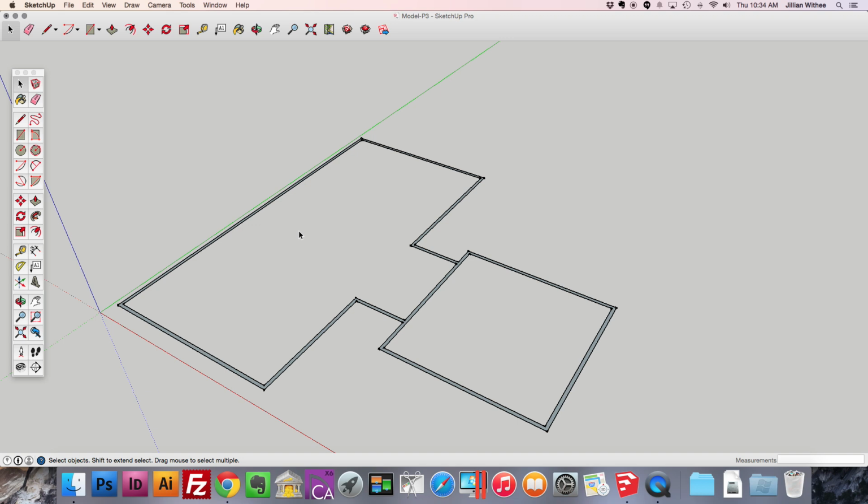Today we're going to continue learning how to draw a two-dimensional floor plan in SketchUp. I have the basic shell of a house here, my own house, that I drew from the image available on the assessor's website for my property, and I printed this out to scale, and then I used that print as the basic starting point for sketching in the interior walls with the dimensions. And now that I have all of the dimensions written down for all of the walls and the window and door openings, I'm going to get started by laying in the walls.